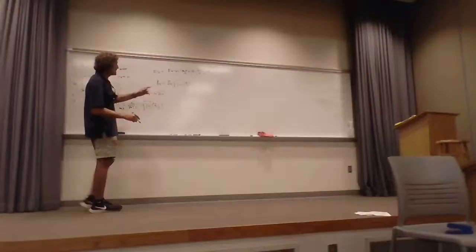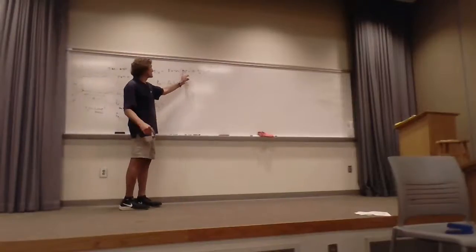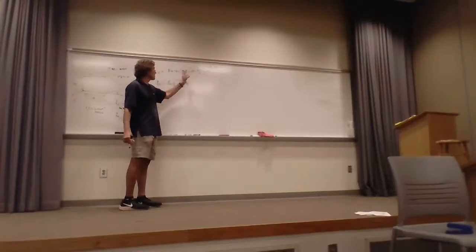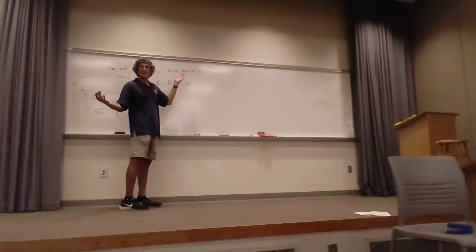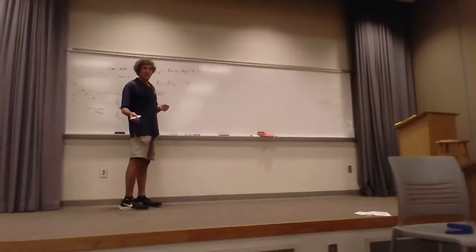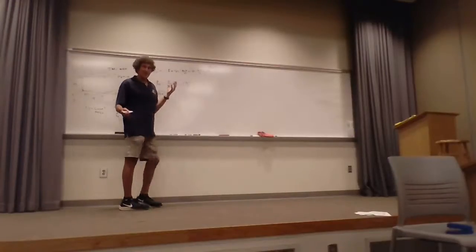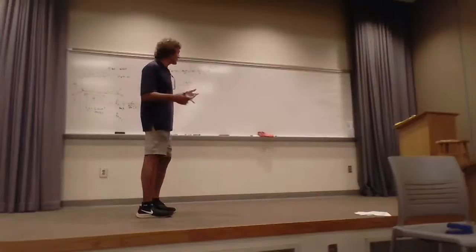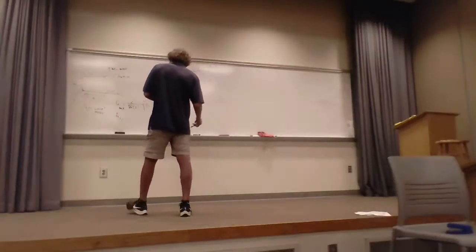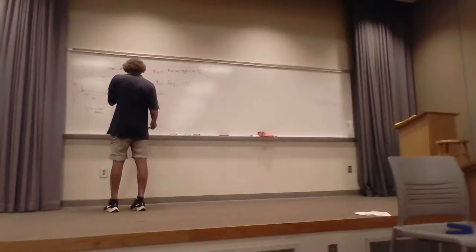And the reason is because if you try to get to a 0,1 or a 1,0, then the sine of 0, you got nothing. Y'all follow me? So there is no 0,1 or 1,0 mode for TM propagation in a rectangular conducting guide. No. The lowest possible frequency will be the 1,1 mode.